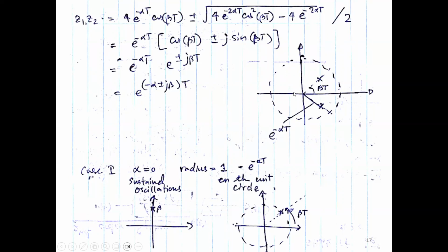When this reaches 180 degrees, you are at the verge of aliasing. That is actually the Nyquist rate. If you calculate your t for 180 degrees and then take the reciprocal of t, you get the sampling frequency. You know that, no? Frequency is equal to 1 over t. And that is the Nyquist rate.